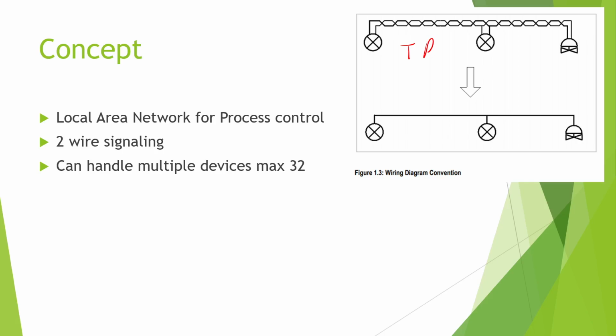Right? Another example, I should say, is in the solar world. All of our diagrams for how things get wired together are one line. But it's like, oh, I've got 6 solar panels wired in series that have 2 wires and a ground, and then I've got 3 sets of those all in parallel. And I'm like, no, we're not going to draw 12 lines that go from point A to point B. We're just going to draw one line, and we're going to have some more information maybe somewhere just to tell you that it's 6 in series, 3 in parallel, or whatever the case is. And as the installer, I can look at this and go, oh, okay, I need to run these wires based on this information. It just simplifies the drawing.